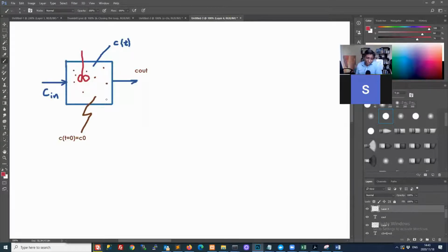So you've got your concentration here, which is the same at all points across that whole reactor, right? Now, if the concentration is the same at every single point in the reactor, then that's going to include the point at this exit point here. And that means that the concentration here will be identical to the concentration in this pipeline.